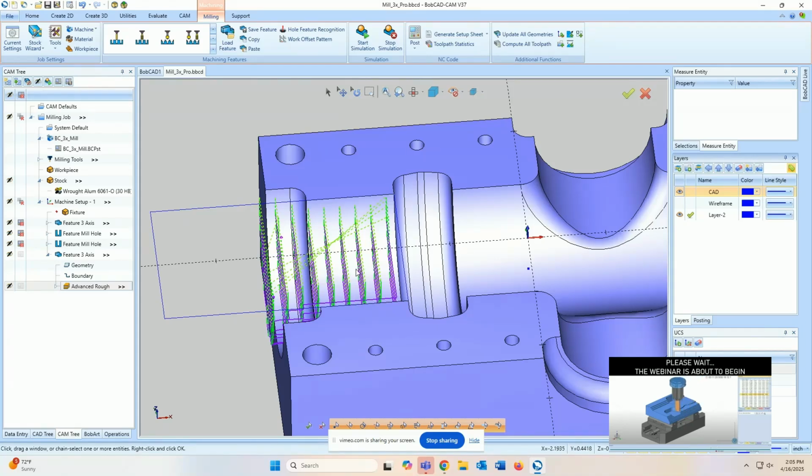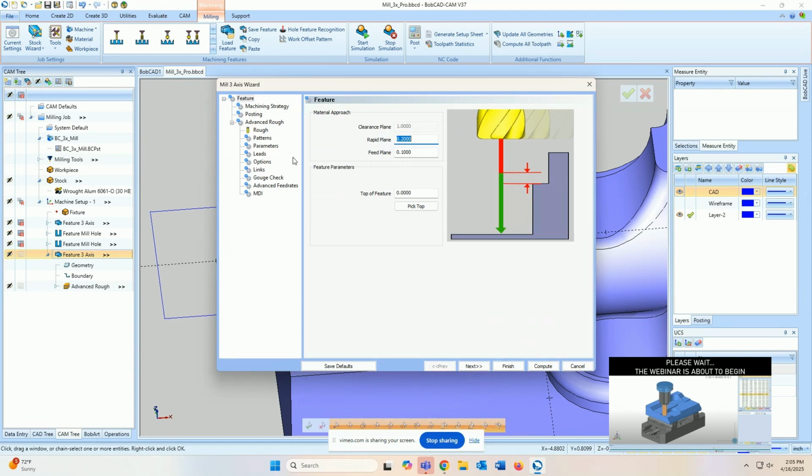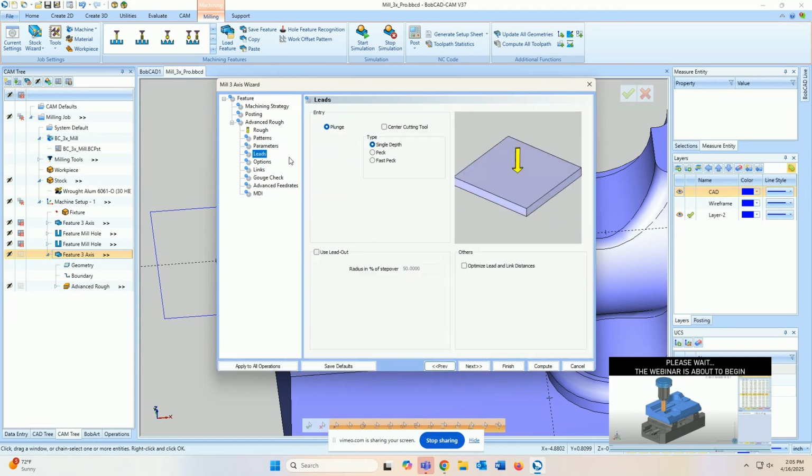I get that sometimes with customers. They ask, why is there no toolpath at all? Because when you are trying to do the side roughing option, you need to have some area where the tool can be outside of the stock and come in with the side of the tool. If it's not physically possible, it's not going to show any toolpath at all.